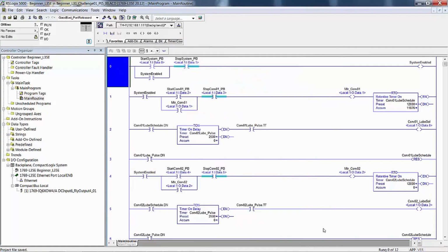The main routine has grown to a size that is cumbersome for screen captures. For this reason, we're going to introduce a new subject, creating subroutines. This feature of RSLogix 5, RSLogix 500, and RSLogix 5000 is analogous to taking a book that is written on one continuous length of paper to a book that has pages and chapters.